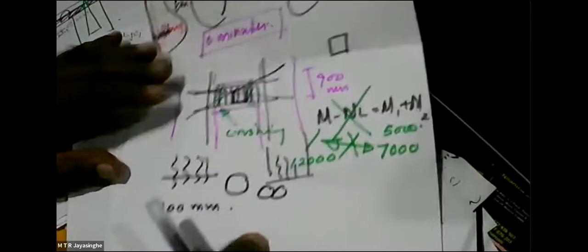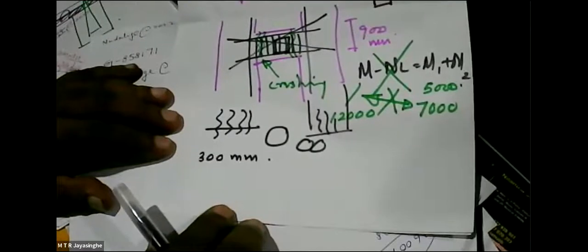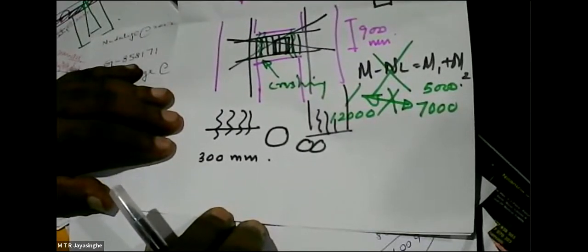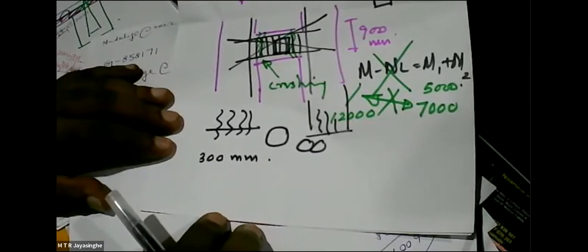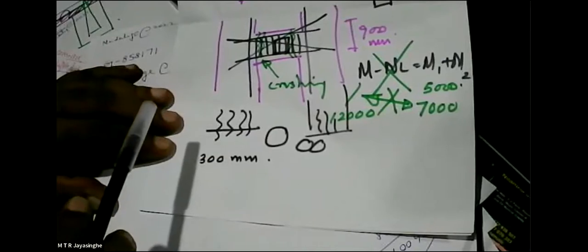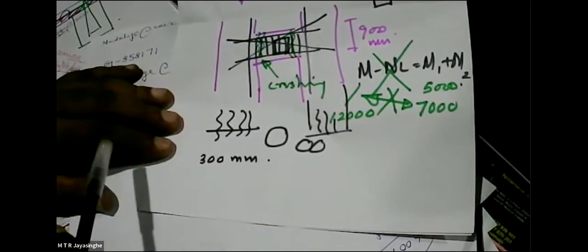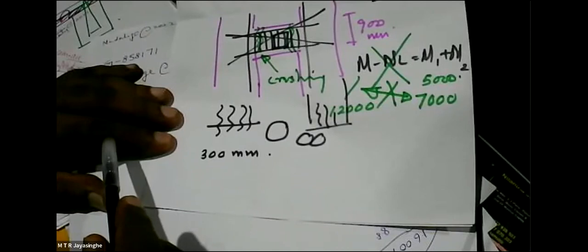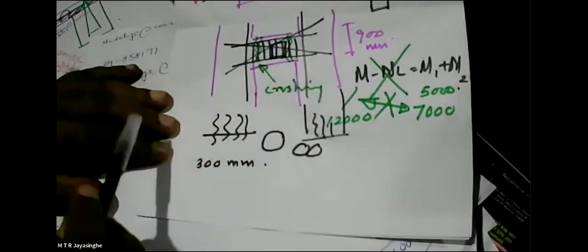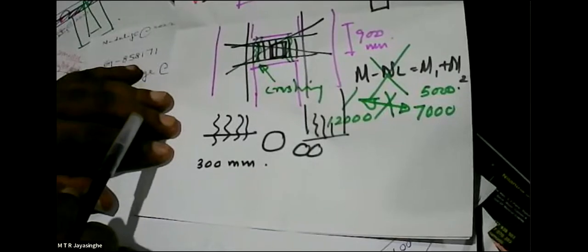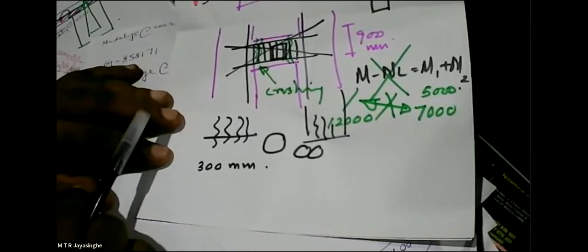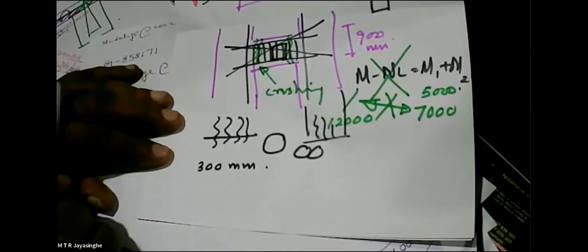So there will be many things that you have to do. Basically, you can see it's very important that we understand all these situations. And if you think you are in a high earthquake zone, it's very useful to have these diagonal bars. Otherwise, if you think you are in a very mild zone, reinforce the beam properly and provide some bars in the diagonal direction. And knowing that you are going to need some diagonal bars, think about it when you are selecting the thickness. Don't just go for any thickness.